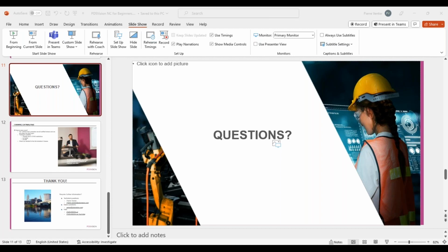So use layers to control the datums and the coordinate systems that you want to see. I know when you have a lot of parts, they become a real problem. It's difficult to see what's going on, and the normal on and off will hide everything, and sometimes you still want to see one or two of those. So layers would be the way to handle those.